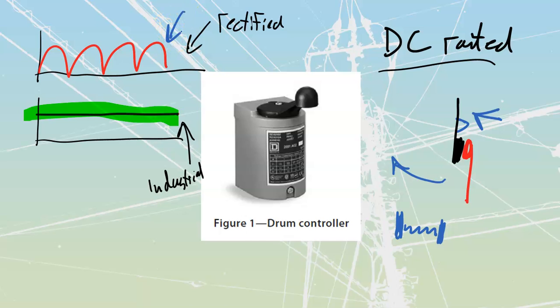This over here, my rectified types of DC or AC as well, cross through my 0 axis or get down to a value of 0 volts 120 times a second, right? 60 hertz, and it goes through once on the upswing, once on the downswing. So 120 times a second, we hit this 0 volt, which means that my arc for a split second is going to extinguish, and then it's going to have a harder time trying to reestablish, etc.